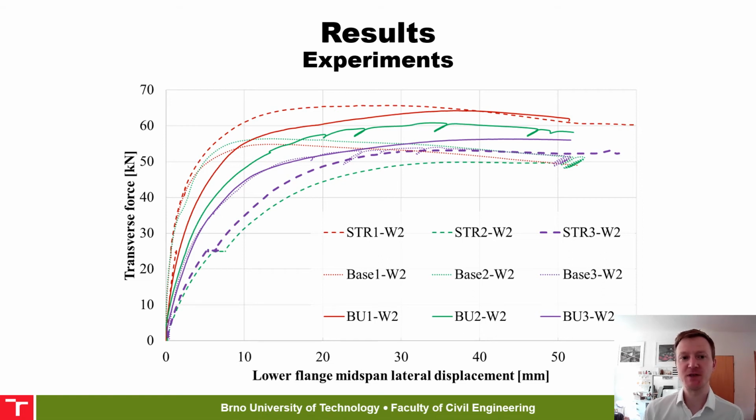Two of the specimens strengthened under load actually withstood the lowest load, so at this point, the design of experiment failed miserably, and the members were not strengthened but actually weakened. Welding under load increased the imperfections for beams with already high initial rotation. That is this horizontal part of the load deformation diagram. Overall, the stiffeners provided about 10% more load resistance.